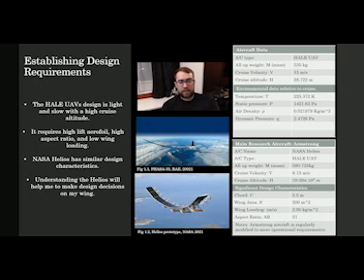An example is the NASA Armstrong Helios. It has an extraordinary wingspan of 80 metres and a wing loading of less than 3 kilograms per metre squared. These extreme design features meant that the Helios had to be made from lightweight composite materials such as carbon fibre. It has no taper or sweep, but has a 10-degree dihedral to provide lateral stability. The Helios fulfills requirements similar to mine, so I'll use the research to help enforce design decisions.